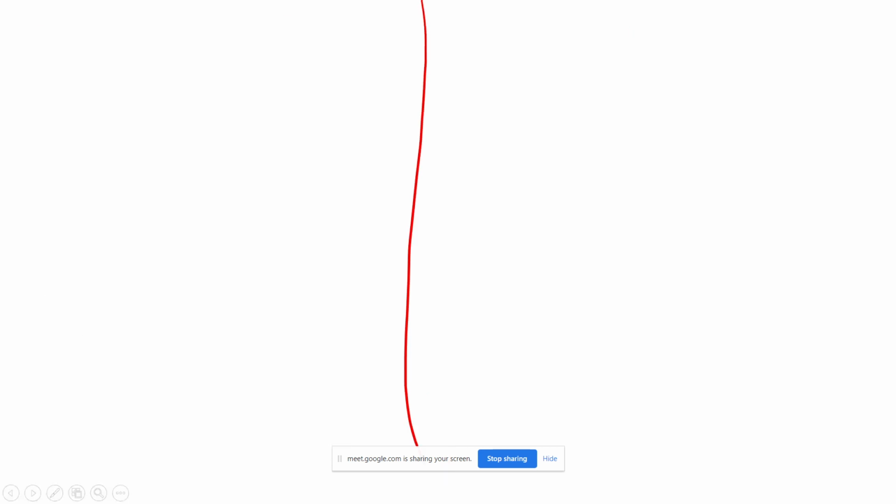So what are the drawbacks of the Carnot cycle? Do any of you know the answer? Isothermal process may not be possible, sir, because in boilers and condensers the pressure drop will occur.